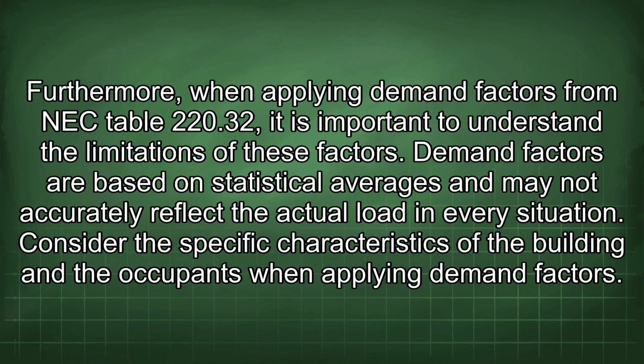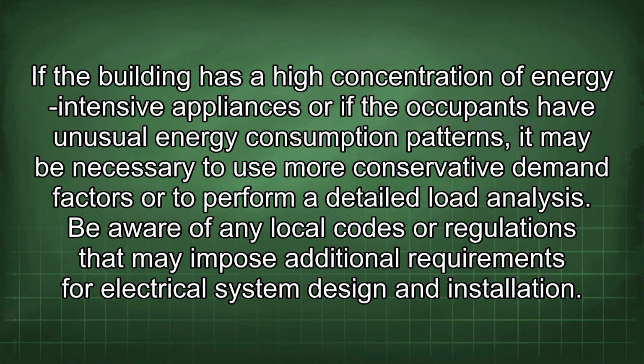Furthermore, when applying demand factors from NEC Table 220.32, it is important to understand the limitations of these factors. Demand factors are based on statistical averages and may not accurately reflect the actual load in every situation. Consider the specific characteristics of the building and the occupants when applying demand factors. If the building has a high concentration of energy-intensive appliances, or if the occupants have unusual energy consumption patterns, it may be necessary to use more conservative demand factors or to perform a detailed load analysis.